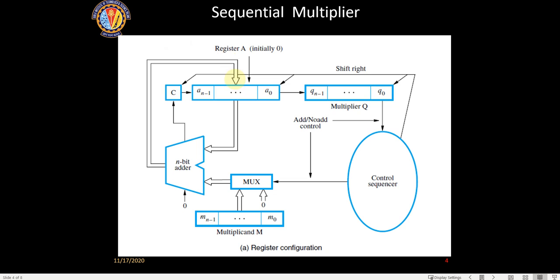During the positive going edge of the clock, this data will be loaded into this register. So whatever is being added here, 0 0 0 0 will come here, carry also will be 0 here. And suppose instead of 0, it were 1 out here. So you have 1 available here. If it is a 1, the mux will take the multiplicand and add it to the accumulator. The accumulator was 0 here, so the multiplicand will get added here, and then that multiplicand will be available out here.